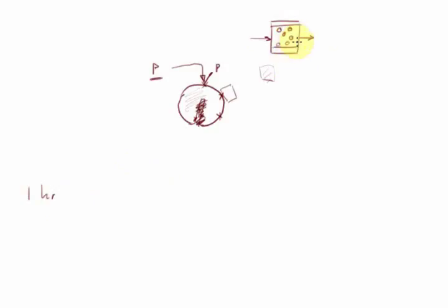So you could look at some way of periodically withdrawing catalyst, reactivating it somehow, and then reintroducing that catalyst to your reactor. We'll talk about regeneration loops later. So regeneration is a possibility. In other words, as part of your process, you include regeneration possibilities. That's what we would do if we have a short time scale for the catalyst deactivation.